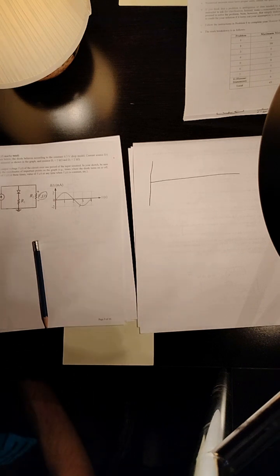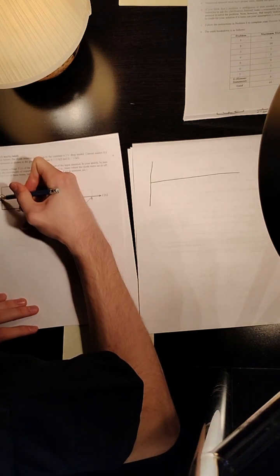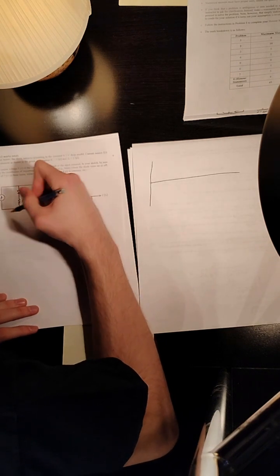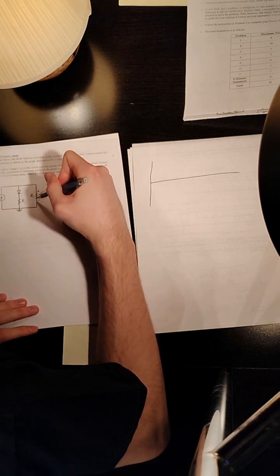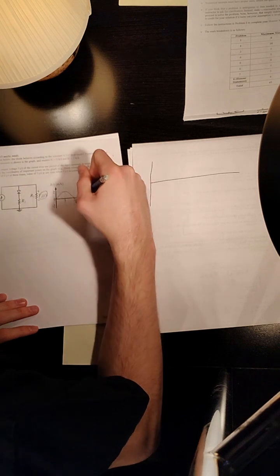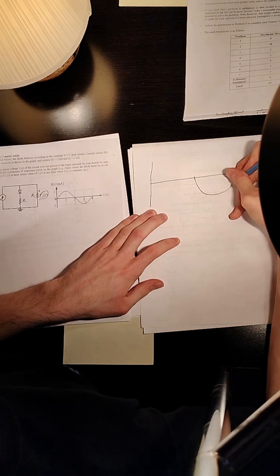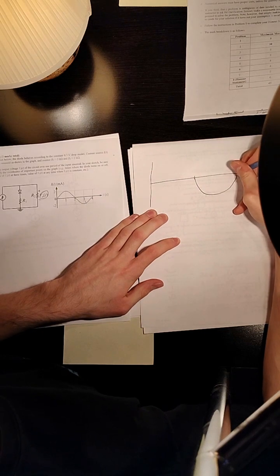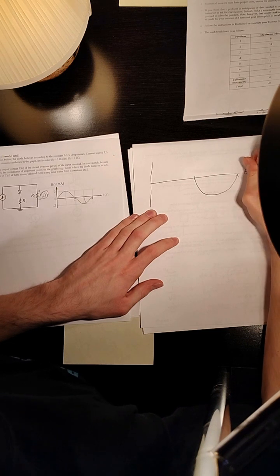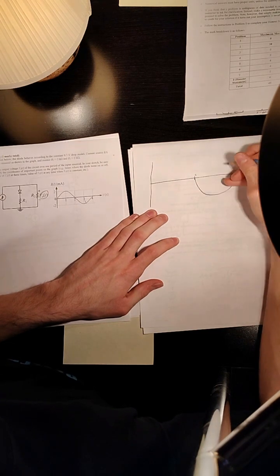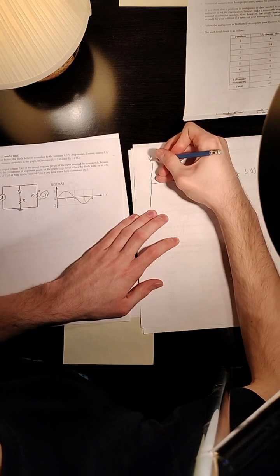And so, in fact, if the current is negative, then your current needs to return, and it's not returning through the diode. So you can pretty well assume that the diode is going to be off for the negative half here. So we could just straight up draw that in. That just looks like that. This is t in seconds, being 2 and 4. And this is VO of t.